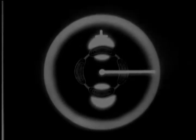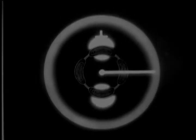Another method of PPI operation employs two sets of deflecting coils which do not rotate as the antenna turns. Instead, the flow of current through the coils is regulated so that the resulting electromagnetic force causes the baseline to rotate. For instance, if current flows through these two coils with this polarity, the electron beam or baseline is deflected to one side, so. But if the polarity on the coils is reversed, the baseline is deflected to the other side, like this.